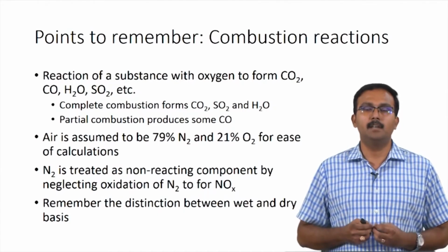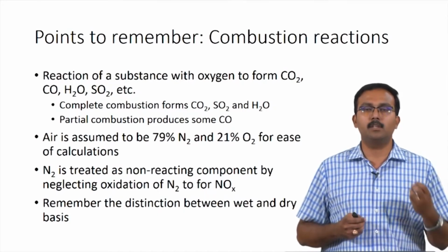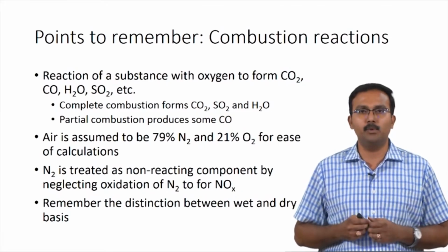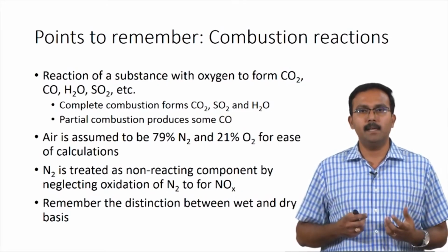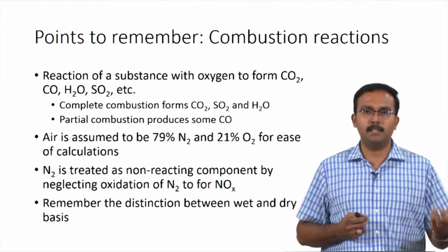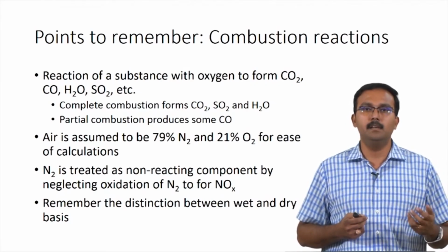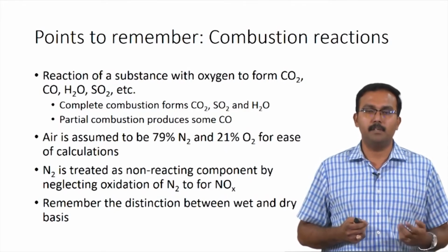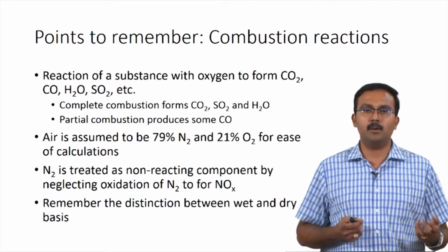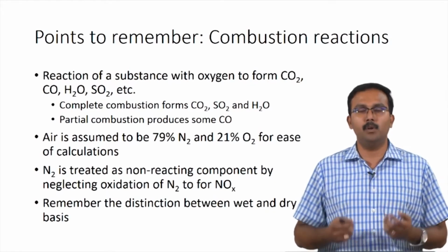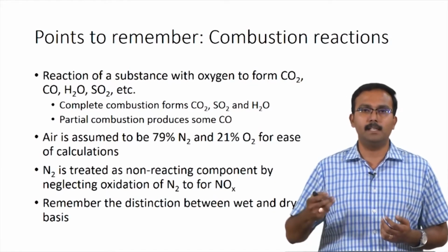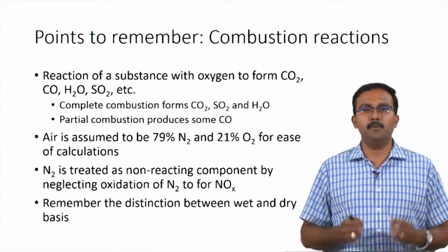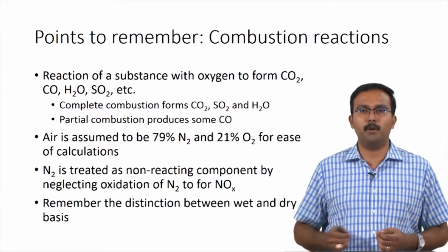So, if you have 10 moles of carbon dioxide, 10 moles of water vapor and 10 moles of carbon monoxide in a flue gas, then in dry basis carbon dioxide mole fraction would be 0.5 and carbon monoxide mole fraction would be 0.5. In wet basis carbon dioxide and carbon monoxide and water vapor would all have mole fractions of 0.33. So, this is what wet and dry bases are. When information is given we need to use them appropriately.